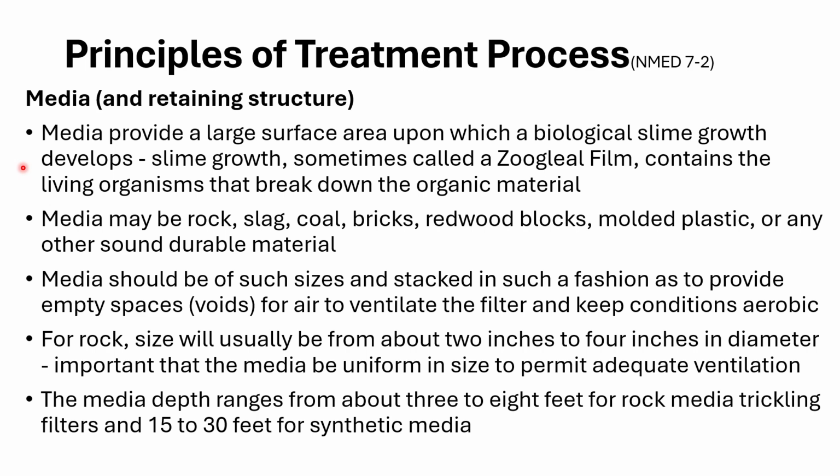It provides those living organisms that are going to chomp away or metabolize and break down the organic material of the wastewater coming into the trickling filter. So the media can be rock, slag, coal, bricks, redwood blocks. You can even see plastic, some molded type plastic media, which are like spheres with rings around them. And again, the whole idea is to maximize surface area. If it's a sound durable material that allows a large surface area, you could probably use it.